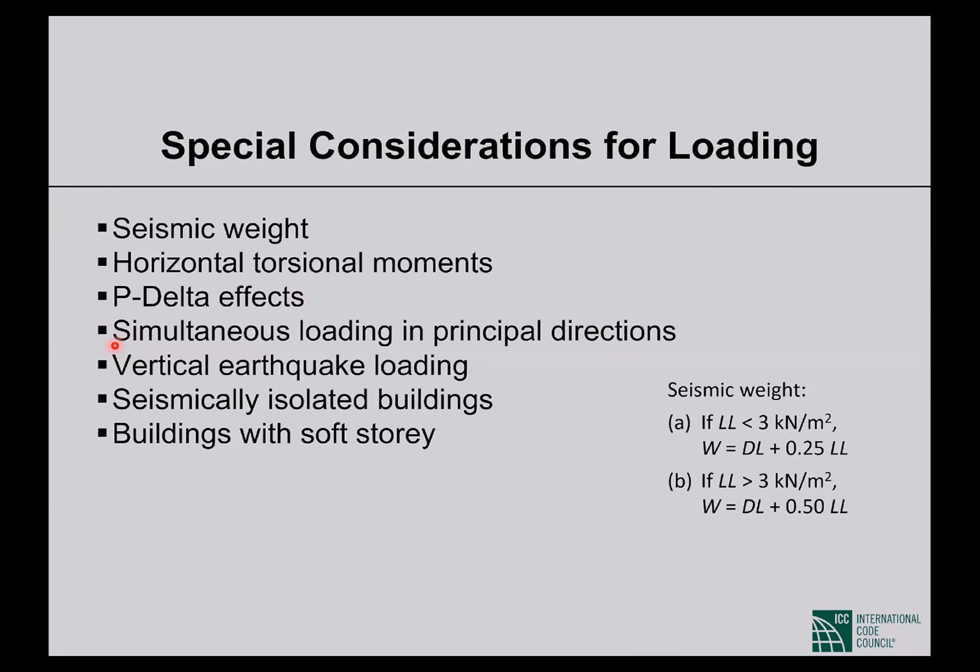Simultaneous loading in principal directions. In the previous version of the code, we used to calculate earthquake load only in the X direction and only in the Y direction, and then we had to analyze the two cases separately. But this time, when we consider load in the X direction, at the same time we have to consider 33% of the load of the Y direction simultaneously in most of the cases.